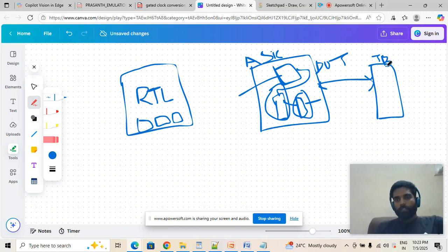Now the thing is, you cannot directly go from this level. Okay, fine, now I have done my design and my synthesis, and you cannot directly go for this. Now you can go for the implementation point of view. Maybe you can go to the backend tool and do the physical design and implementation. Do the layout, routing, everything. You can do it.